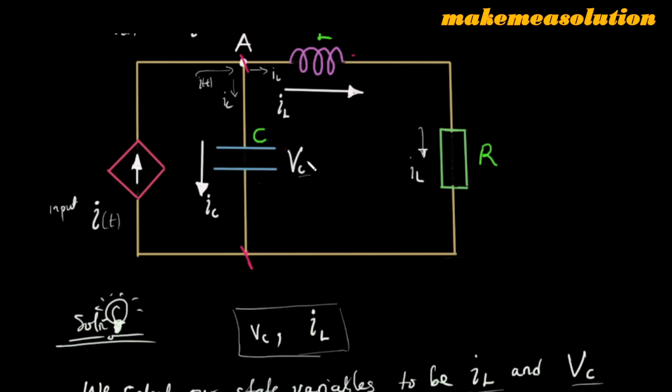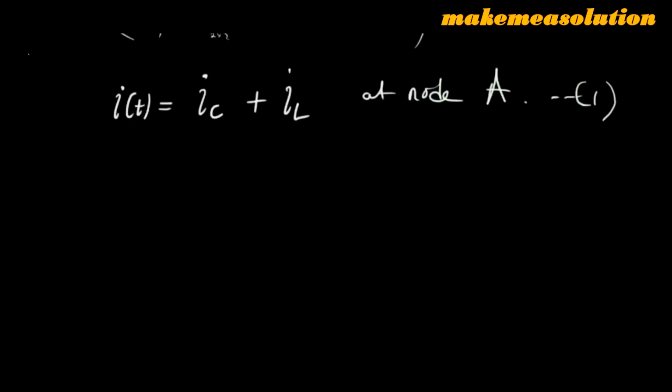In other words, just like energy is conserved in the principle of conservation of energy, the potential energy supplied, in terms of voltage, this VC will distribute into this VL and this VR. So another equation you could get from this system is VC is equal to the voltage across the inductor plus the voltage across the resistor. The potential across this point is the sum of the potential here and the potential here. So we write it like that in our equation 2.